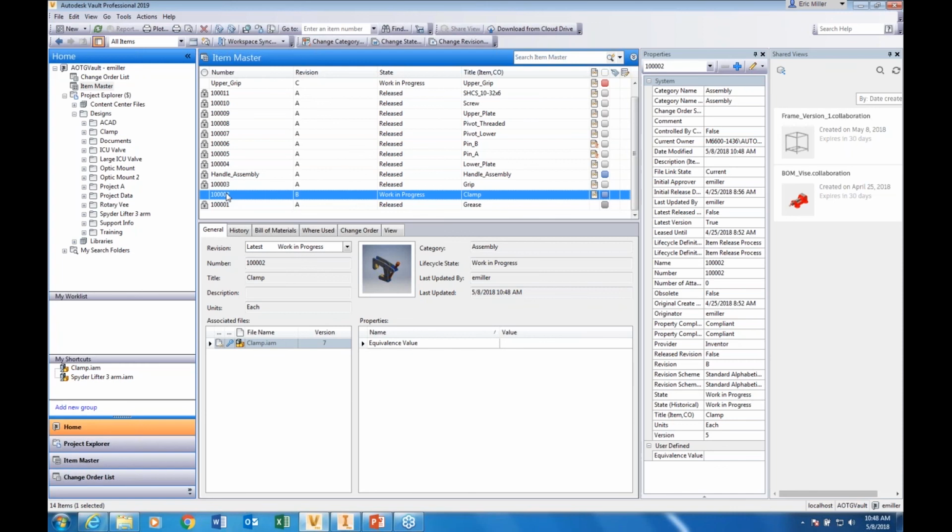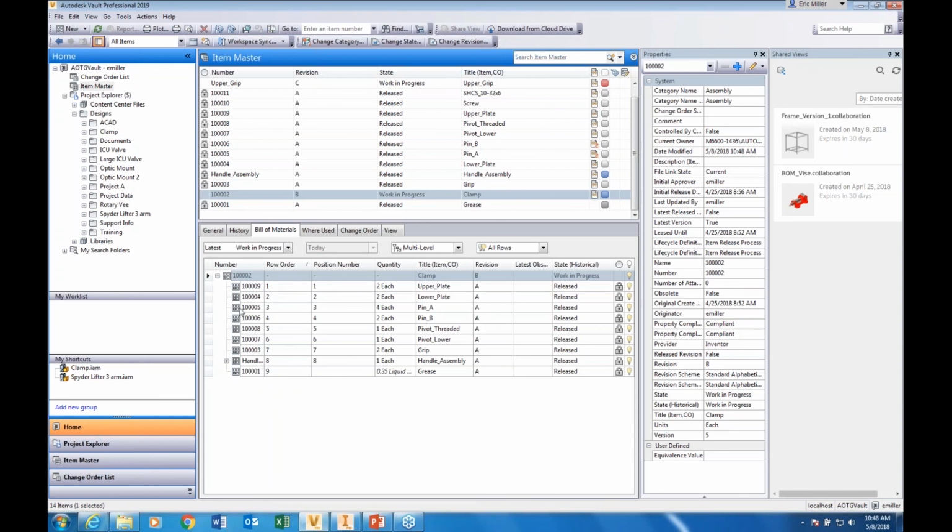I would say it's around 50% of our customers who are actually utilizing that, depending on their needs. But this bill of materials section, notice I'm in the item master, can be nice because maybe your CAD structure isn't always the appropriate way you want your bill of materials to be shown. So out here we can adjust that, add stuff, delete stuff on this bill, or maybe package it up a little bit differently. Like your manufacturing might assemble two components together, and you want that to be listed as a sub-assembly on your bill of material items.